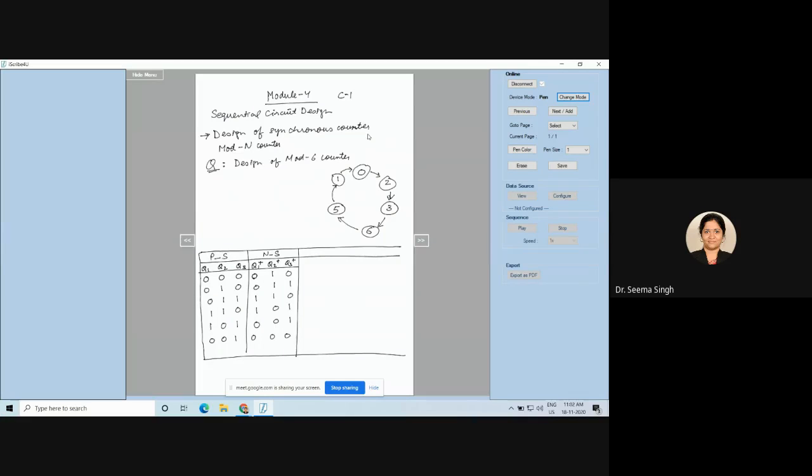Now, when I have three variables, I will require three flip-flops also. So now what you need to design is the flip-flop inputs. This is a little trivial for you people to understand at once. I want the design of the mod 6 counter using JK flip-flops, starting with the most difficult flip-flop only. Using a JK flip-flop means that if I want the change of state from Q1 to Q1 plus, this can be done using one JK flip-flop. So for the state change from Q1 to Q1 plus, I will say that I have a flip-flop whose inputs I am calling J1 and K1.